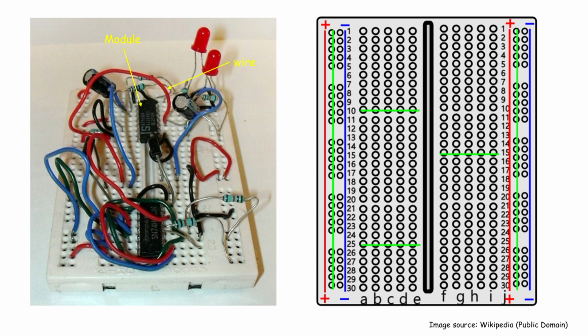We can think of each physical component plugged into the breadboard as a Verilog module, and the wires connecting them as wire declarations. Placing components on specific holes is conceptually similar to the placement stage in FPGA implementation, while connecting one component to another with wires resembles routing in FPGA design. In a way, designing with an FPGA is like connecting ICs and wires on a breadboard, but it's all described using HDL, hardware description language.